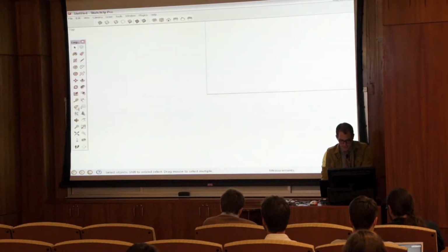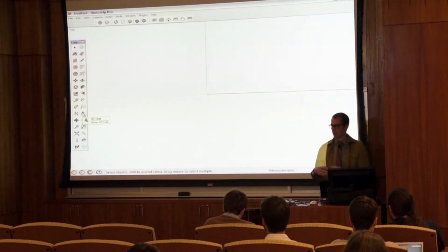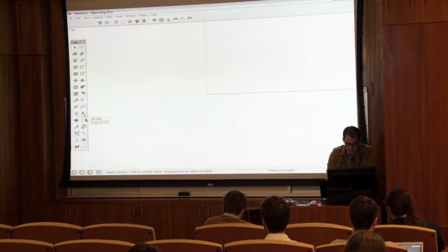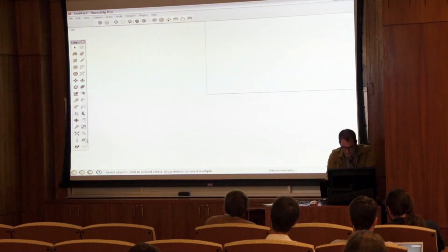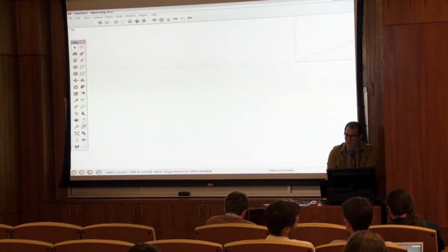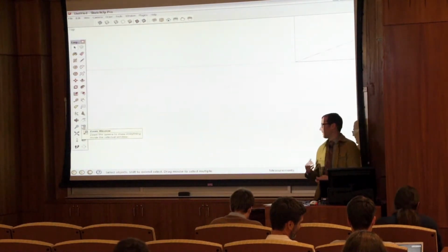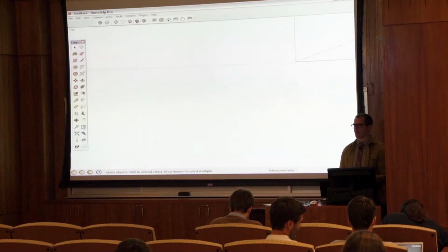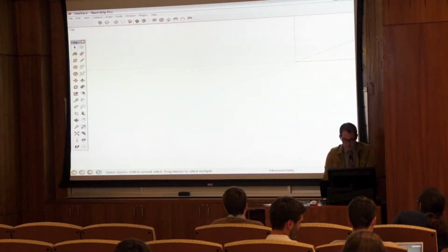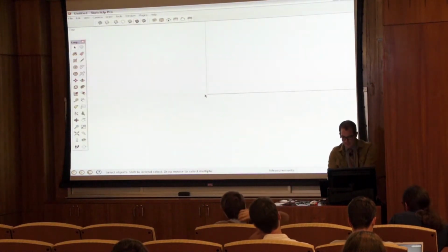These are more annotative tools like tape measure to measure distances, to scale models, your dimensioning, protractor to measure angles, 3D text tool, which is great if you have to put 3D text along an item. And then the last 10 tools are more or less dealing with orbiting, panning, and zooming, which is very critical in SketchUp or in any 3D modeling program. Get fluid with orbiting, panning, and zooming because you spend most of the time doing that versus actually modeling. So I'll give you some tips and tricks as we get into 3D for some of these tools.